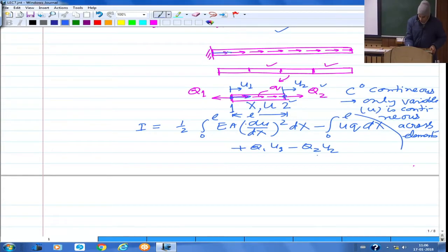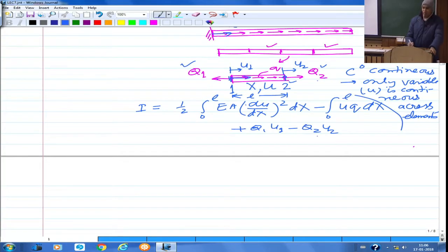And the sign convention, for the displacement, we are always taking displacements positive along the positive coordinate direction. Here we have taken a global axis x, so the displacement u at all points is taken as positive along the positive x direction. But when we are showing these section forces, here the outward normal is along positive x, so this force is shown along the positive x direction. This is also a positive section force, but since the outward normal is along the negative x direction, this force is shown along the negative coordinate direction. A positive cross-sectional force is shown along the negative direction on a negative face. So these are basic sign conventions you use even in the concept of hysteresis.